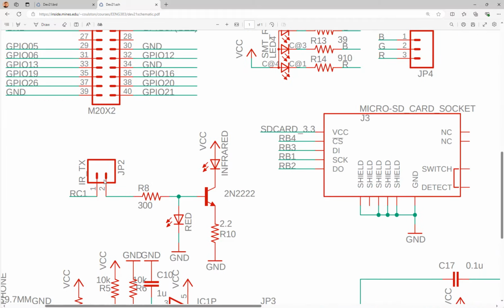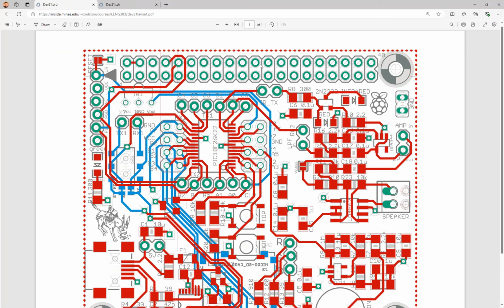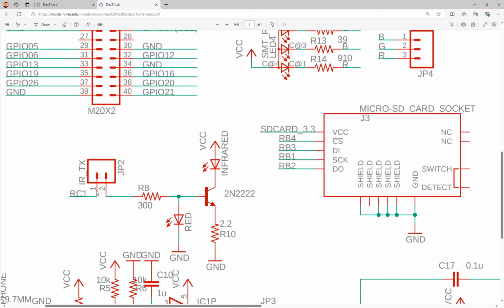What's going on here? RC1 is a pin. So we use the pin to control the LED. Makes sense. So RC1 comes in, but there isn't a connection if you don't put a jumping wire or jumper over here. So you put a jumper over it, making the connection. Which means the electrical signal being sent by the microcontroller through PWM, so the pulses, will be sent through this jumper to the BJT, which is the switch, turned on and off, and here's the IR emitter. Okay? So you are controlling the base.